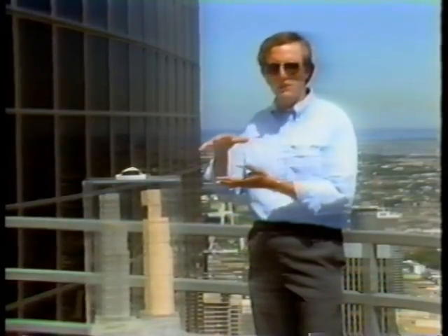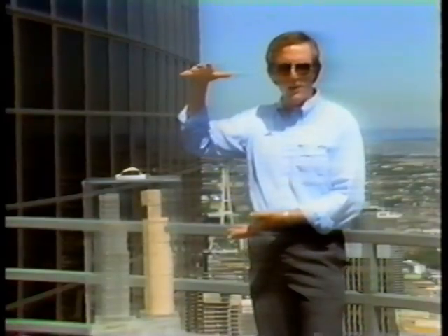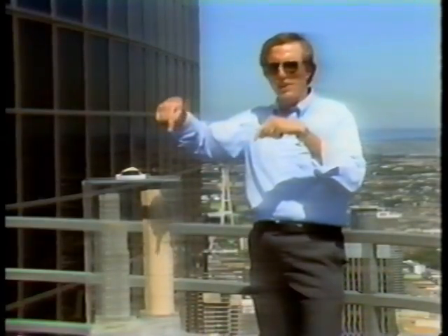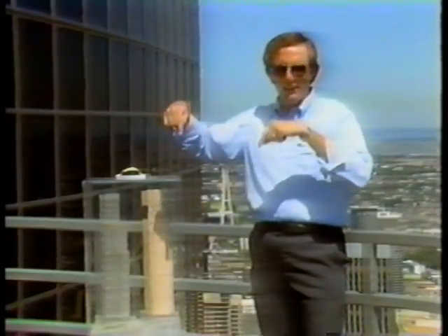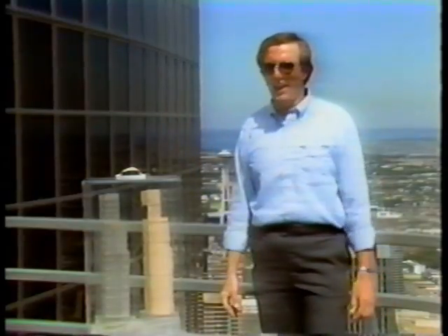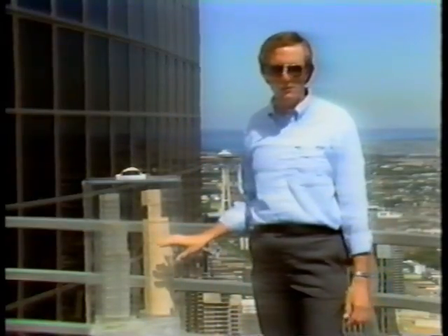And the reason for this is that as the wind blows on the building, its pressure as a function of time and position on the building is very irregular. And these fluctuations in pressure cause vortices to build up at the sides of the building. A vortex is like a whirlpool of wind, and periodically these vortices are shed from the side of the building, and when they're shed, they cause large suctions on the side of the building, which pull the building to and fro in the direction perpendicular to the wind. And thus the building vibrates at its fundamental natural frequency.